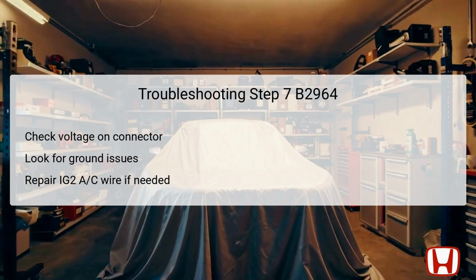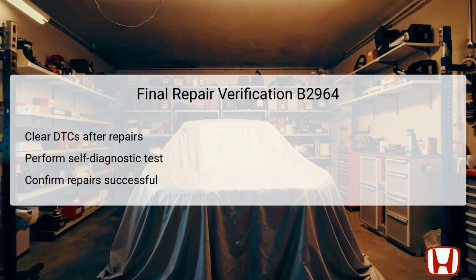If battery voltage is detected, investigate potential breaks in the ground wire. If the ground wire checks out, focus on the ground point at G504 for any faults. In the event that no voltage is present, it necessitates repairing an open in the IG2 AC wire circuit. Conducting these checks is crucial to ensuring that communication between the climate control unit and the front panel does not encounter further interruptions.